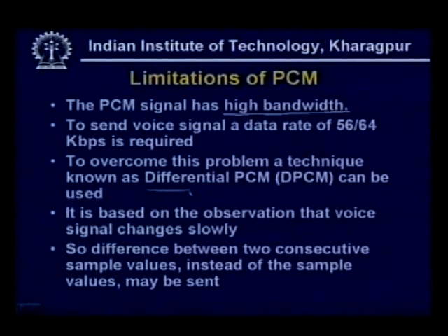Since the voice signal changes very slowly, why not send the change rather than the absolute values? That is the basic idea of differential PCM. Instead of sending the absolute values, the difference between two consecutive sample values may be sent. This is the basic idea of differential PCM.